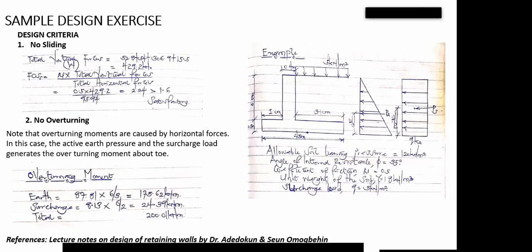Now, how can you take moment? You can only take moment by being strategic with your resultant force. I know that the area of my X is 5.5 times 3.1. That is this particular place. Because this is uniform in section, the resultant, if I want to convert that uniform earth material load to a point load, is going to be acting at the center, that is for vertical.